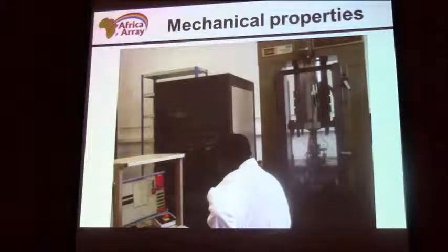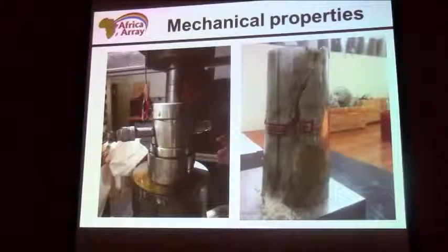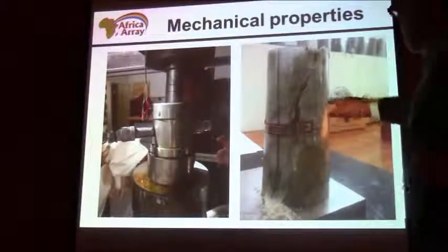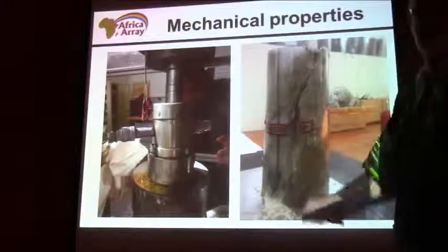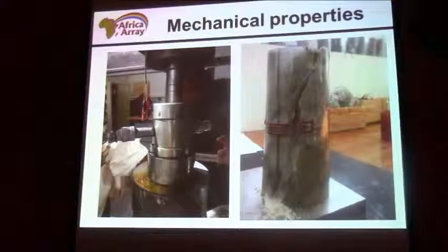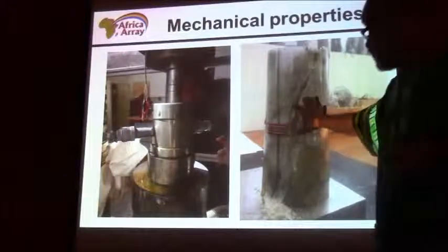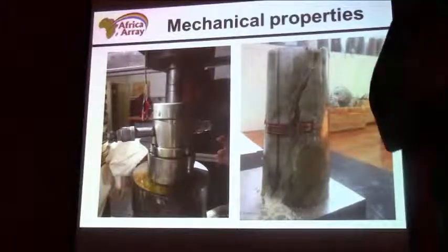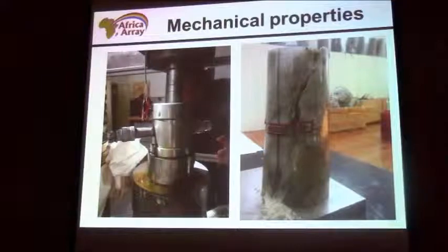Okay, so we want to see what the strength of our rock is, and we squeeze it over here, and afterwards it will fail in some way. Okay, so we can see the whole stress-strain curve, how the rock responds to loading. One thing that we also discover is that your rock becomes a lot stronger if it is what we call confined. If it's just a specimen on its own and it's not confined, it will just crack down the middle at quite a low load.